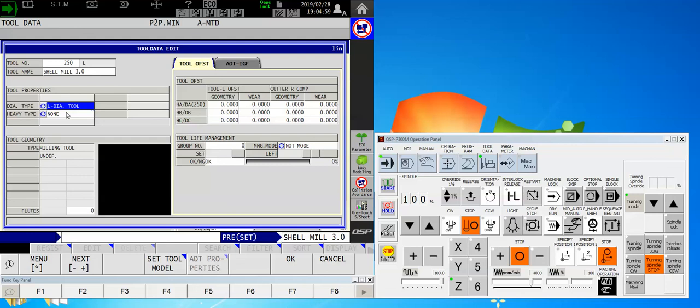It will also do a very wild tool change procedure. It will grab the large tool, the arm will swing in, grab the large tool, move to a neutral position that's about halfway between the magazine and the spindle, and then stop. It will then reorient the tool magazine so that it can put the non-large diameter tool in a pot other than the one that's been saved for this large diameter tool.